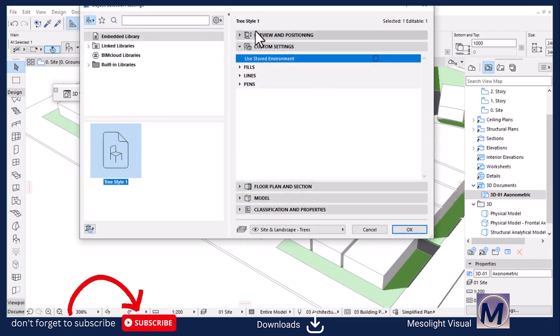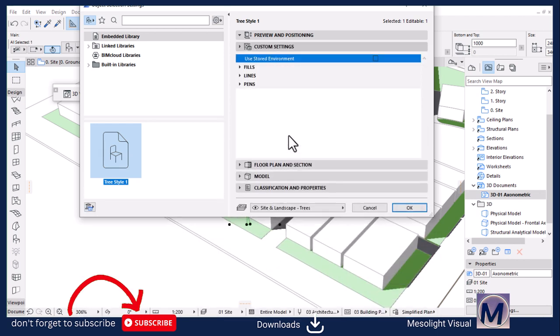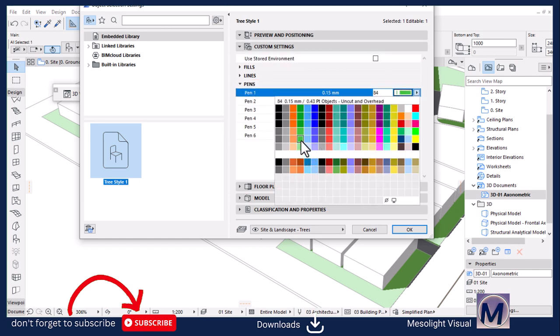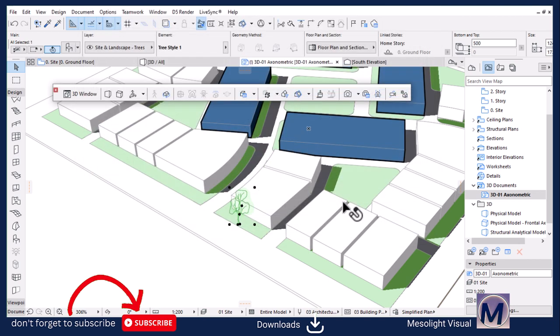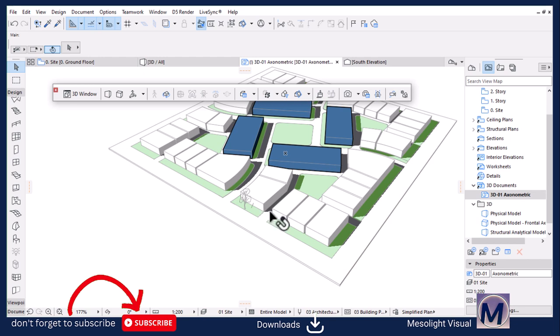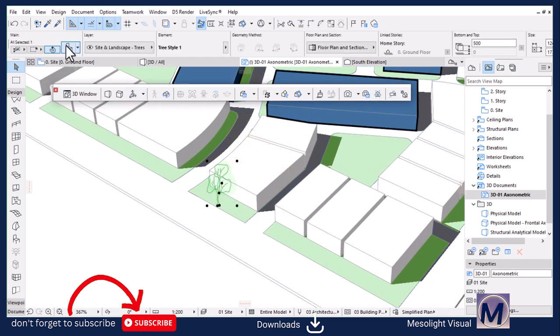Let's open its settings, and then under preview and position I'm going to link dimensions and make this maybe 500. Okay, 500, and go down to custom settings. Under pens I would want a darker pen. Let me say this, and then hit OK. Even if I do, I don't think a darker pen would do.